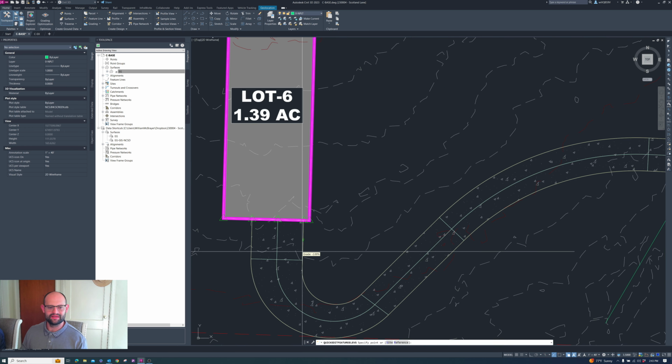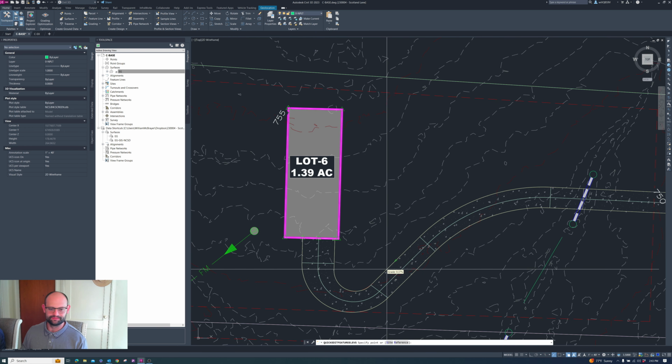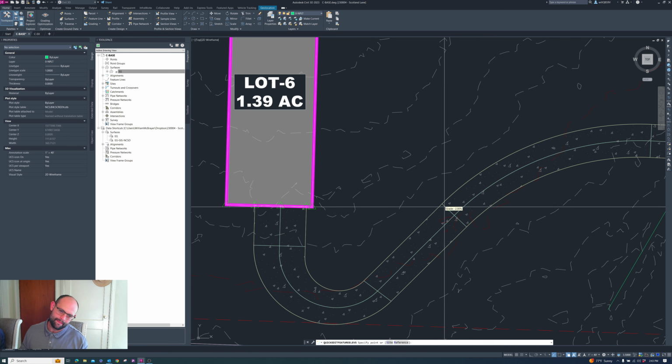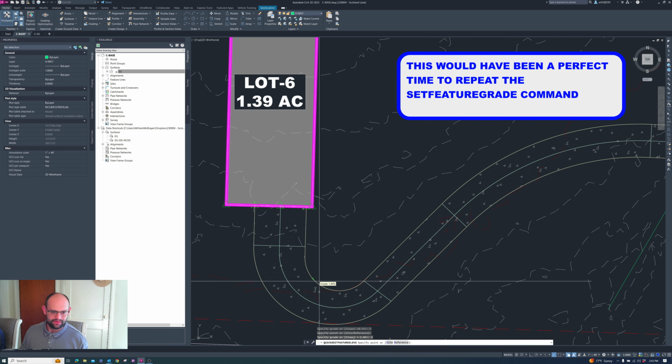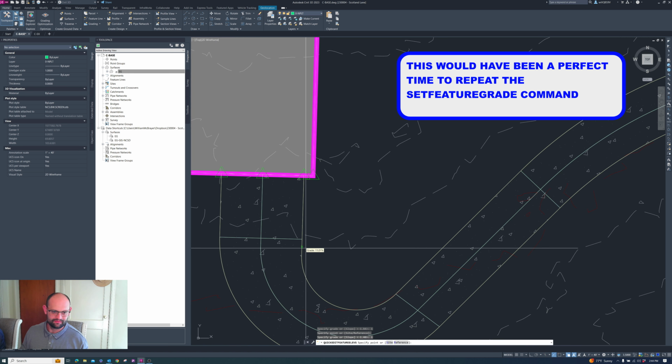Let's see if we can find something that works out a little better. We don't want that to be too flat. Otherwise, we'll need to skip away from this normal crown or generate a ditch that moves a little further away as we work down this way. Let's try going up at 1% here. Just keep that going. We'll work up at 2 there.